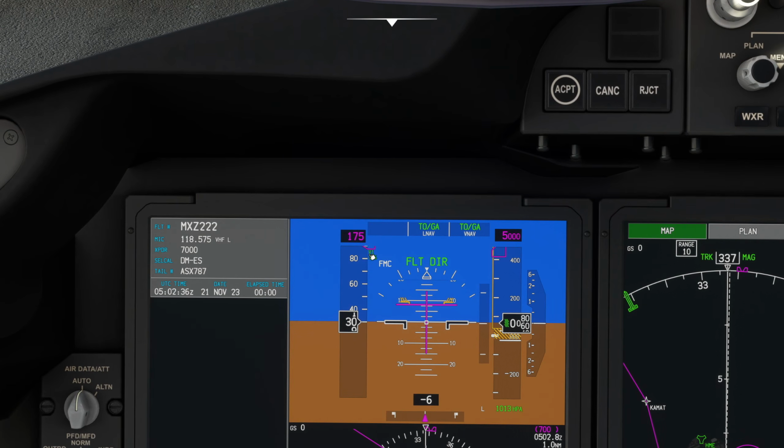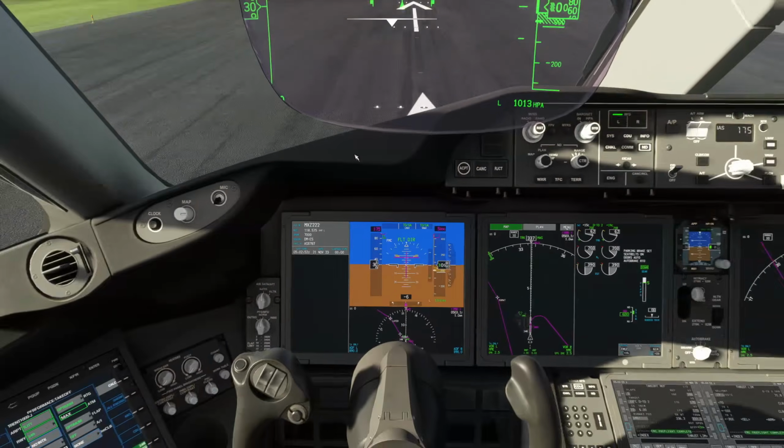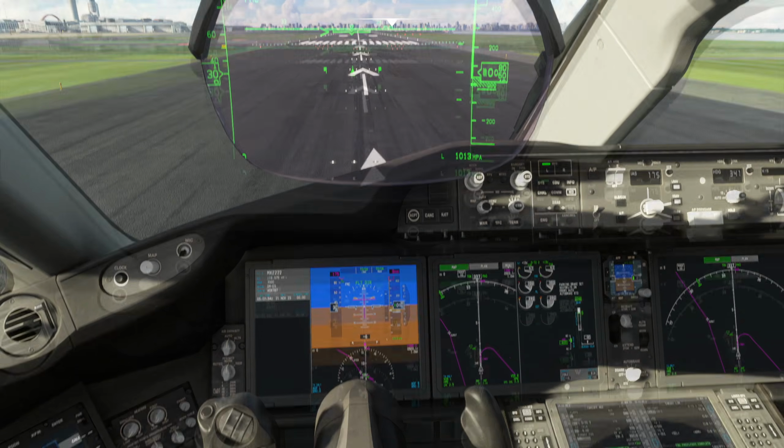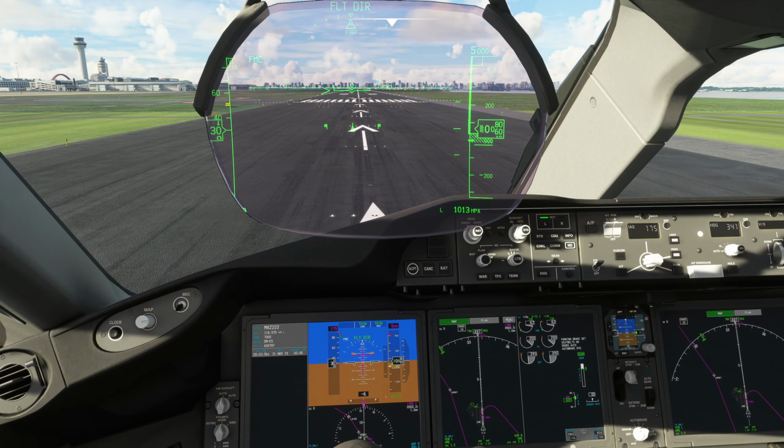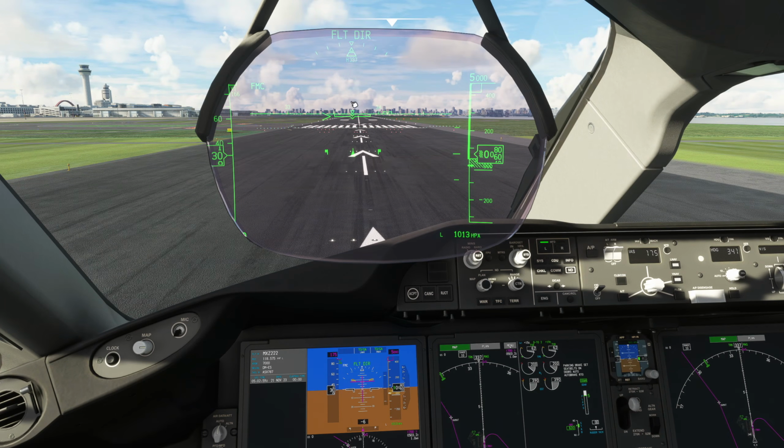The target speed will be set up to the next flap setting limit minus 5, but as you bring in the flap it will then increase further up to where it wants to be. So it's quite clever. It will look like it's targeting a slow speed, but you can actually bring the flaps in and then it will move up later. I'll talk about that once we're going. A lot of this I need to explain as we go, so forgive me if I miss a few things during the takeoff. It does happen relatively fast, but what you will see is we use the whole or a lot of the runway, and it's a very gentle acceleration in order to save engine wear.